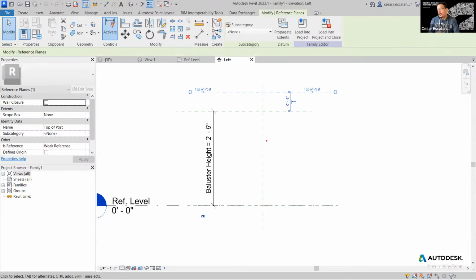And so I'm going to sketch what we're going to do. We're going to create a new profile. We're going to create a revolve. And it's going to have this sort of classical way of doing posts. So we're going to have something like this, an arc, like a chess type of baluster. And then this is going to revolve 360 degrees.